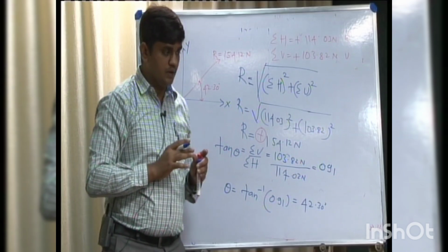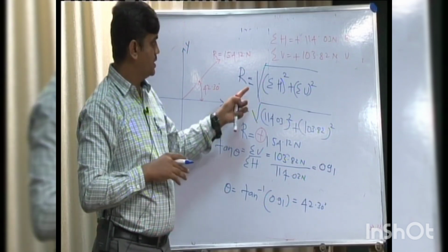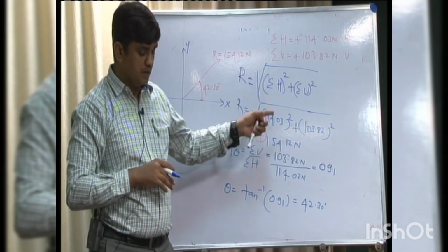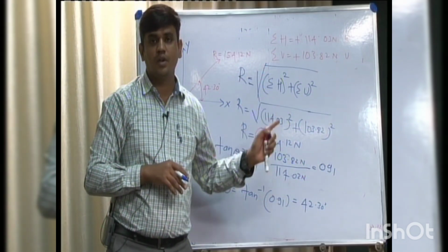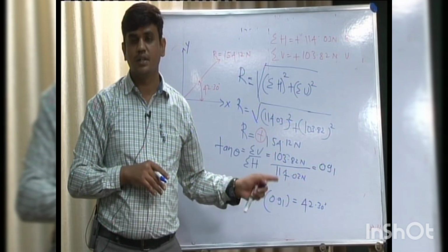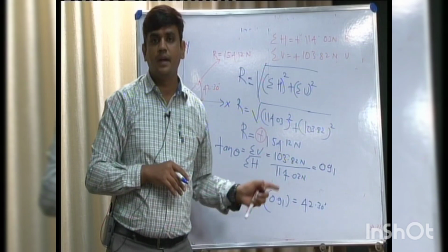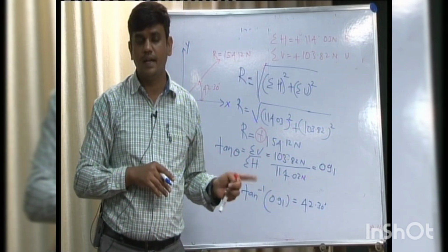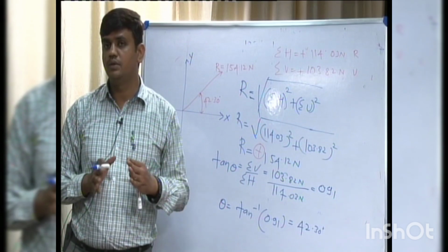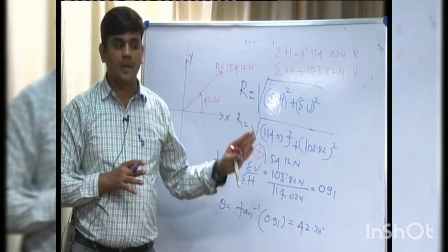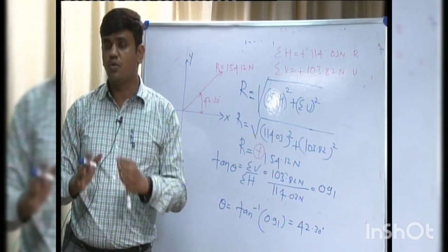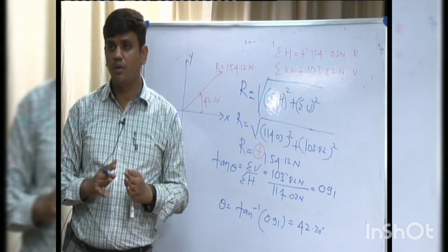The difference between the previous problem and the other previous one is that the angles were not given in what we have just done. So the first point is you have to calculate the angle which is not given using the trigonometric relation, tan theta is equal to vertical by horizontal component, V by H. Then taking the inverse of tan theta, you get the angle, and write down the angle in the coordinate system and start resolving the particular force in each quadrant into horizontal and vertical components.